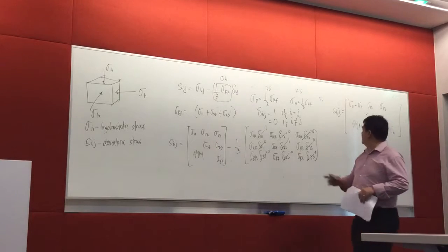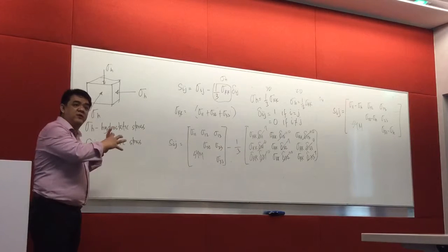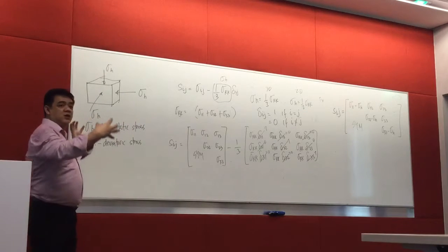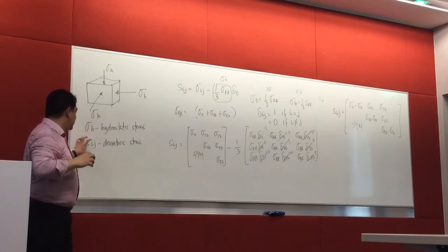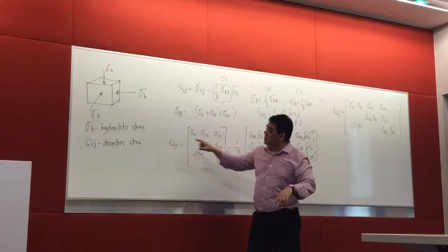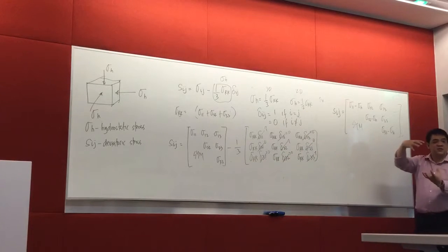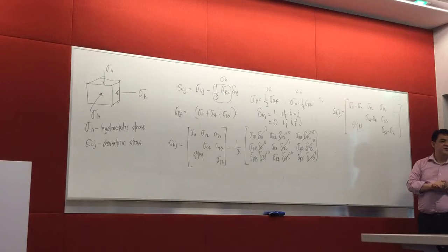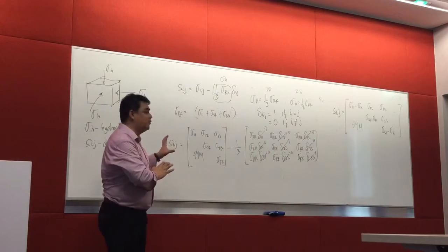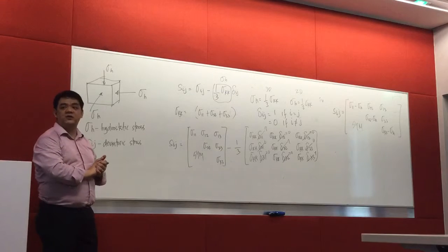So what does this deviatoric stress tensor mean? That will be the stress tensor that's going to cause distortion on your material. So we already removed that element that's going to cause changes in the volume. If you remove this from your original stress component, the one which causes changes in the volume, then you have an expression which changes the shape of your material. So take note, it's not just looking at the equation, it's really trying to understand what this equation means. At the end of your solution, you will be able to explain what's going on.